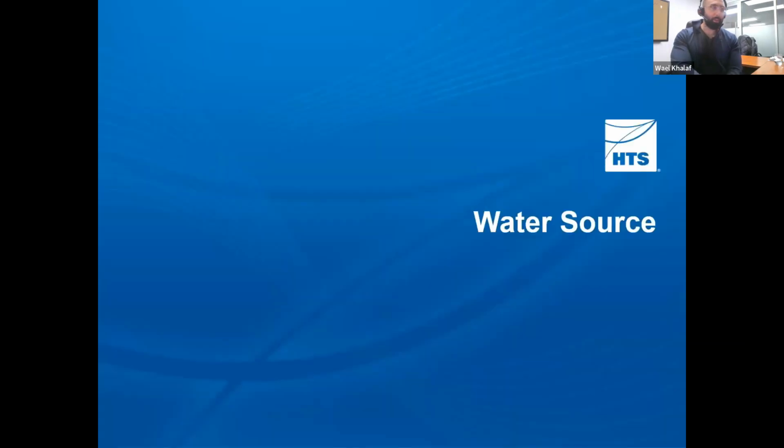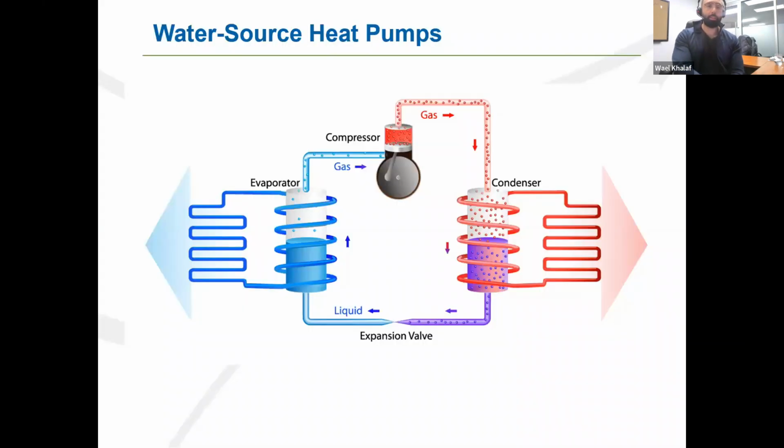So we've gone through the air source nomenclature and types of machines or technologies that exist. Now let's look at our water source heat pump. So again, same concept. When heating with a water source heat pump, we use water glycol that circulates over whatever devices we have. But our source now is no longer ambient air. We use a specific liquid. That can be a condenser loop that's connected to boilers or a cooling tower. That could be a process loop that has waste heat tied to it. Or most commonly, lately we're seeing a geothermal loop. So this is where we're going to dive into your water source heat pump applications.